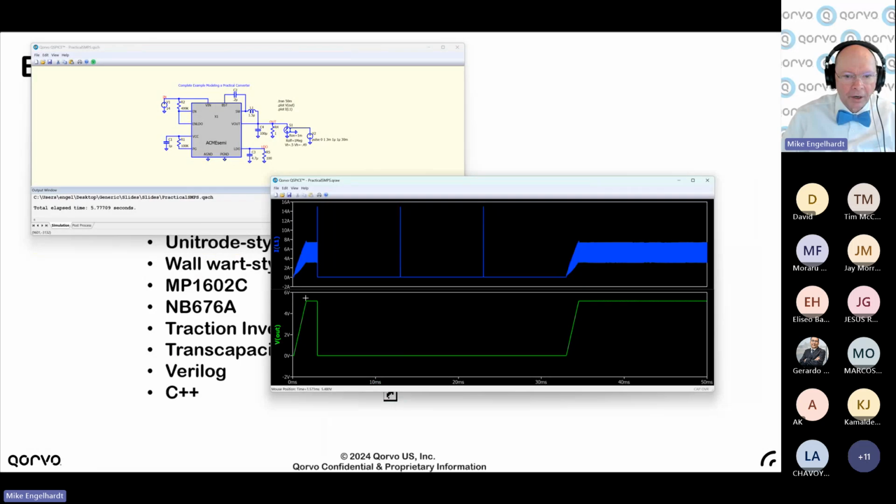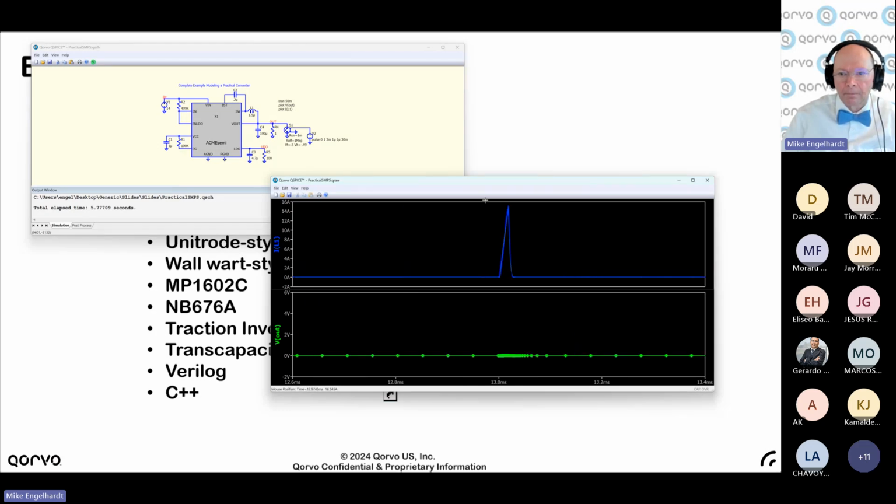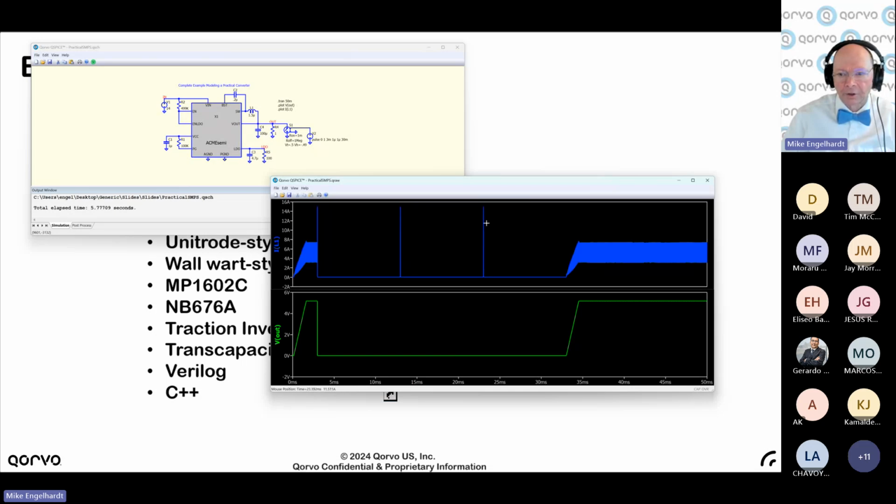it did the normal startup, and then I shorted it. It went into hiccup mode, and here it did a hiccup. It said, "Oh, can I start up?" Nope, too much. I can't start up. So I turn off. I tried again. Then eventually I remove the short circuit. Then I can start again.